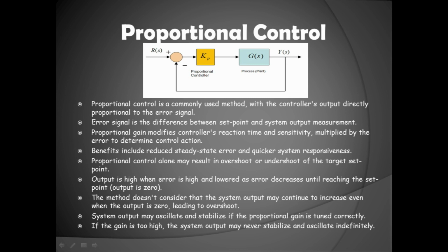Take a temperature controller, for example, that is connected to a heater and a sensor. And we select the number X as our set point. As the controller grants power to the heater, it will be heating up. And the temperature will start to rise until it reaches X. Now, when it reaches X, the controller will disconnect power from the heater.